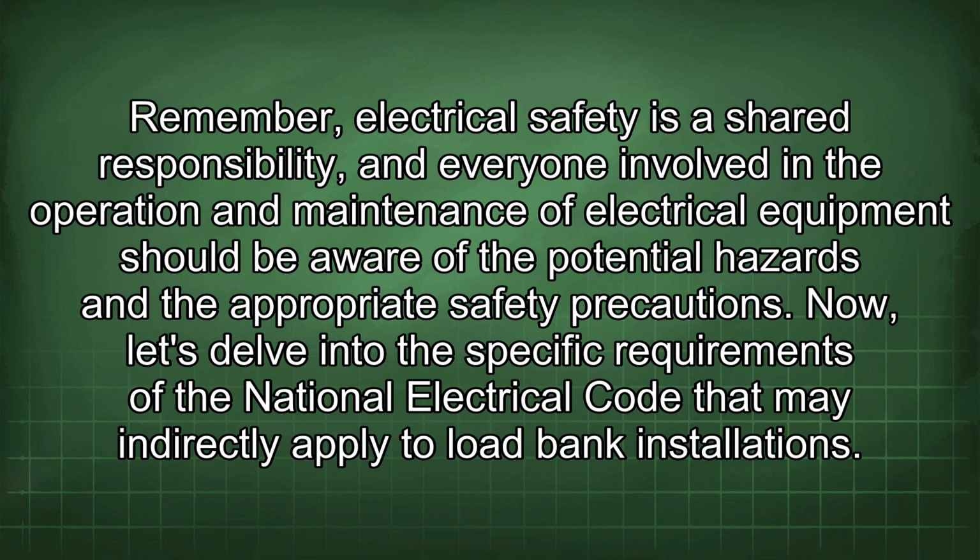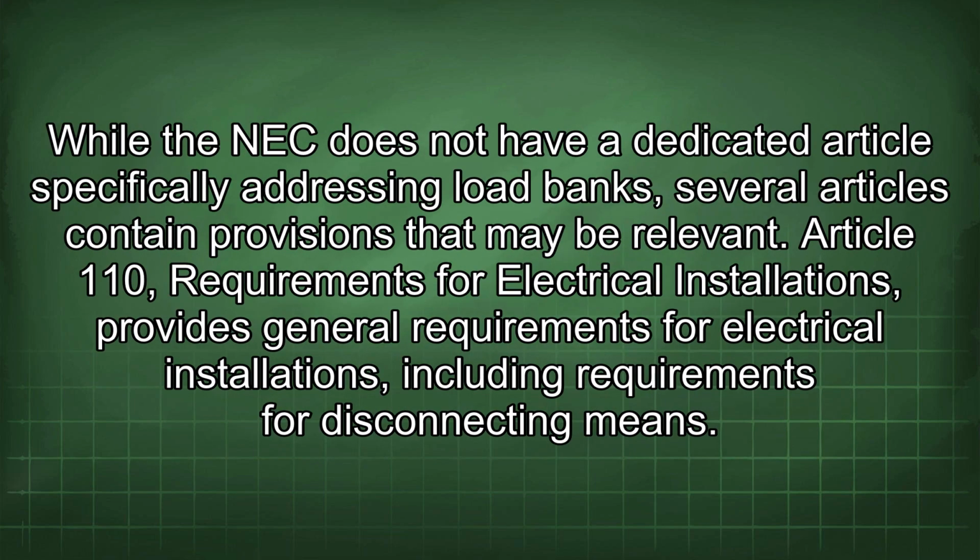Now let's delve into the specific requirements of the National Electrical Code that may indirectly apply to load bank installations. While the NEC does not have a dedicated article specifically addressing load banks, several articles contain provisions that may be relevant. Article 110, Requirements for Electrical Installations, provides general requirements for electrical installations, including requirements for disconnecting means.